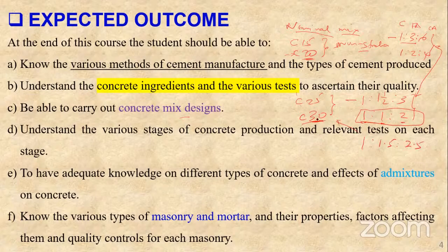So you see, in that case, you have been able to economize because you are using less cement and more of the coarse aggregate and fine aggregate to achieve the same strength. You may go somewhere like the Rift Valley, where your aggregate is pumice, the lightweight. So it's not very strong. Therefore, to attain the same strength, C30, you may need to use less of the fine aggregate and more cement. So you may need to go with 0.9 to maybe 1.8.